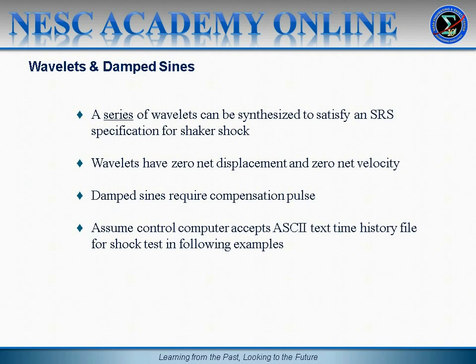So in this unit we will be synthesizing a series of wavelets in order to satisfy a shock response spectrum specification. Now each individual wavelet has a property such that its net velocity is zero and its net displacement is zero, and that is also true for a summation of wavelets. On the other hand, if we were to use damped sinusoids, we would need a compensation pulse in order to achieve zero net velocity and zero net displacement. But in this unit we're focusing on wavelets.